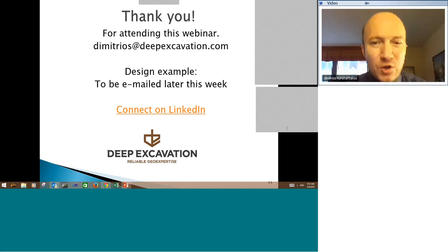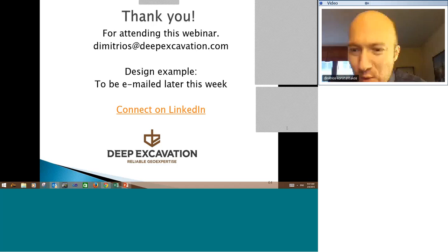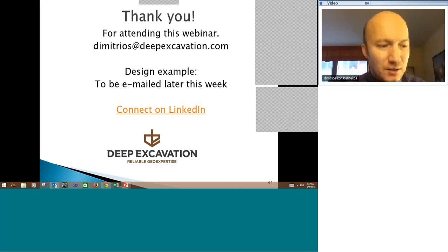So, with Eurocodes and LRFD, it seems that, okay, there's a question from Vivek. How important is time as a factor in deep excavations? Time is important when you have clays, I would say, or time-sensitive soils. If you have clays that behave in an undrained way, then switching from undrained response to drained over the long term can have an impact.